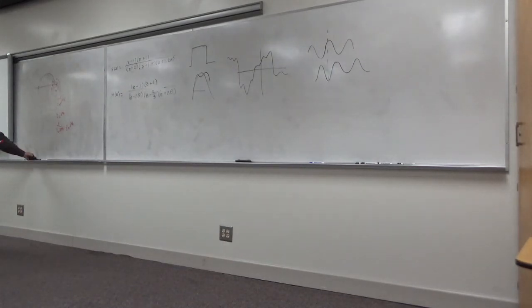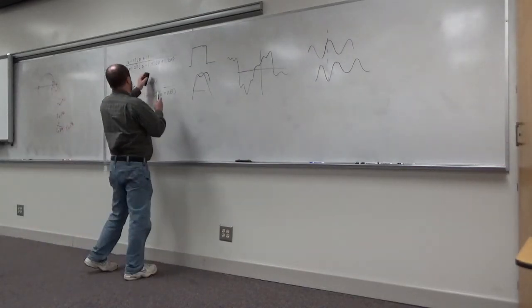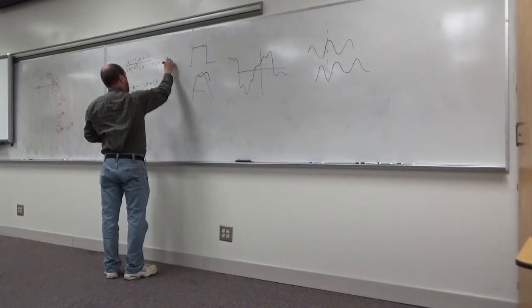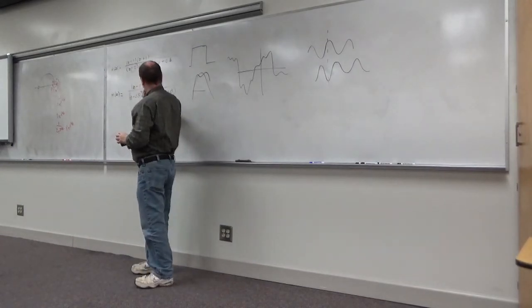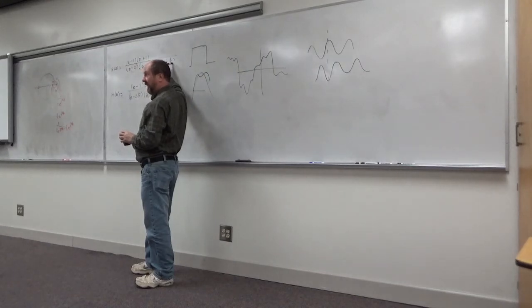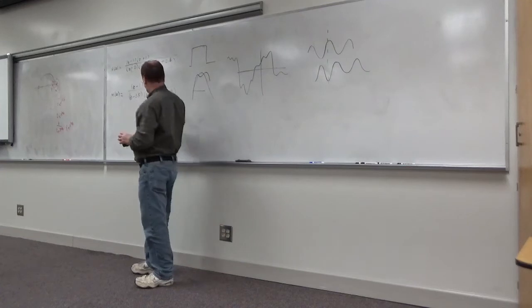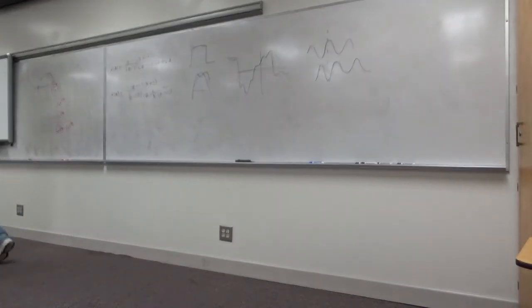One last question on this: what if this one were at z plus 0.8? Could you reflect that one, and leave that one alone? And why would you? Because that one's already inside. Could you leave that one alone? Sure, just reflect whichever poles you don't like. Reflect them inside the unit circle, and the poles that are already inside the unit circle, leave them alone.